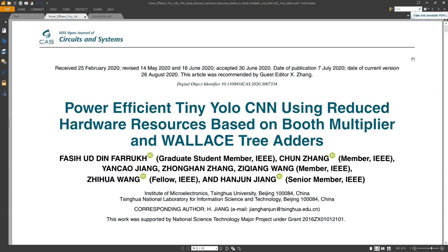The goal of this design is to lower the hardware resources and the amount of power consumed. It has been proposed that the modified Booth multiplier with the encoding technique and Wallace based adders may respectively take the place of a bulky MAC unit and the usual adder trees. The multiplier architecture will occupy a number of conventional full adders. It will take more logic size compared to the XOR-MUX full adder design. Here we present this work with the XOR-MUX full adder design instead of the conventional full adder design.